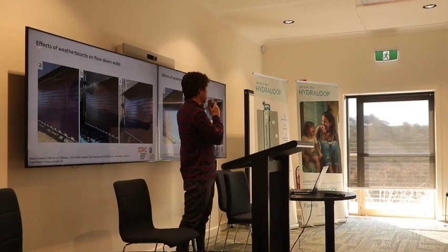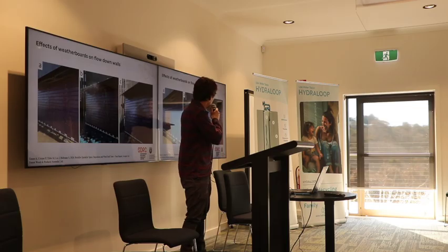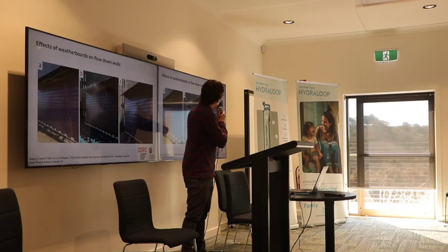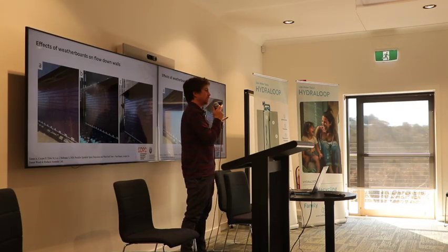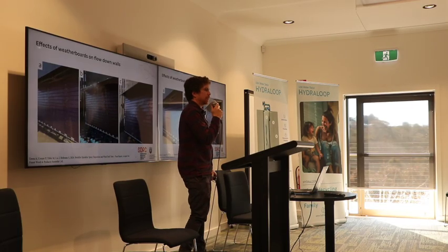But the other one, actually, the spray adhered better to the wall with the weatherboards. And we think it's because it was an impact sprinkler spraying at the wall. Normally it splashes a lot where the jet of water hits the wall. But when the weatherboards are there, they restrict that splashing.